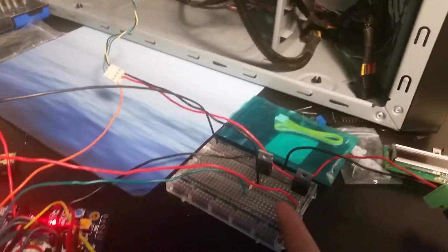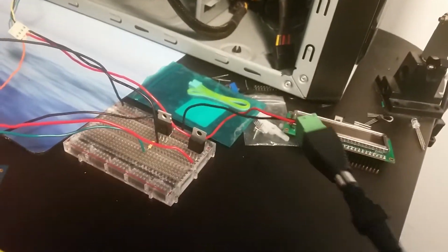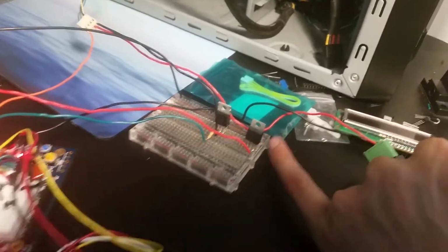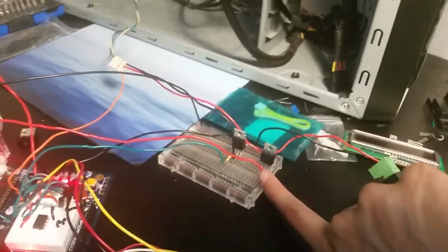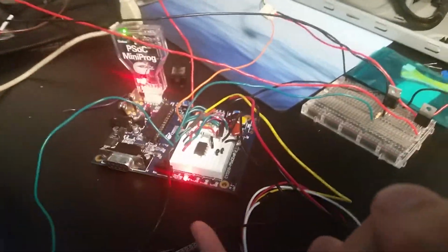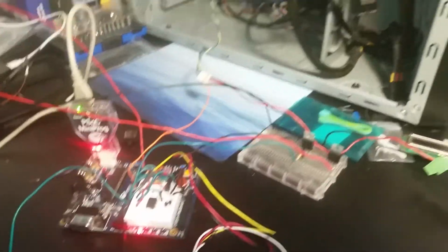an N-channel MOSFET at logic level to switch it on and off with the PSoC since it's on a 12-volt line. I also had to use that regulator on the same line to get 5 volts for the window opener since I couldn't pump enough juice from USB to power up everything.